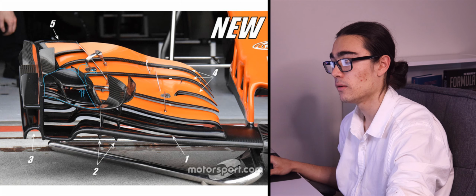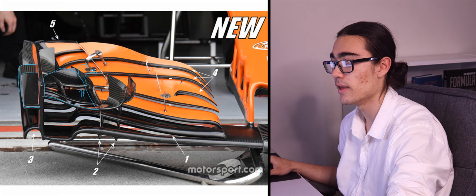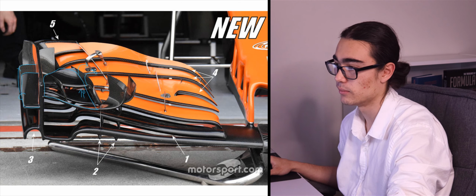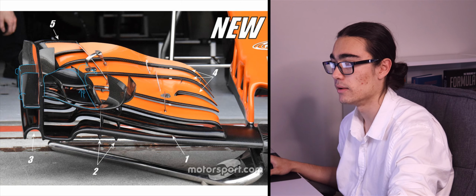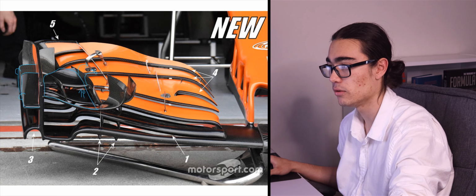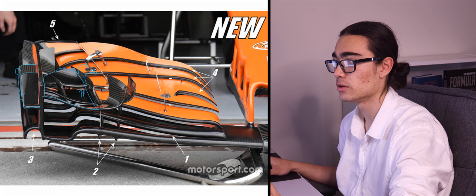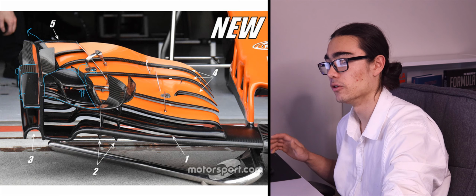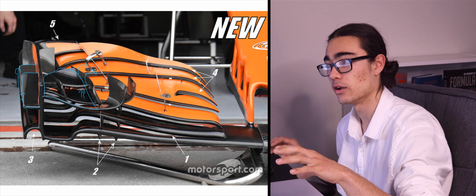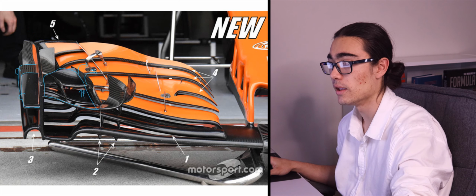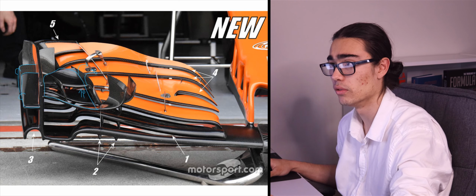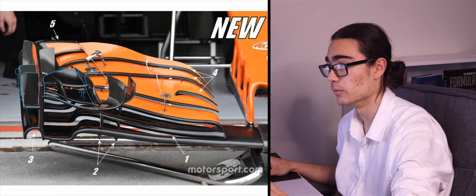Now you've also got your dive planes or canards down here, and they will produce a vortex, and they look like they'll combine together and head quite low, but it's dependent on the elements on the front wing here, what they're doing with the airflow, how high is that going or how low is this going, if we're going to see the interaction that I thought that we maybe would see.